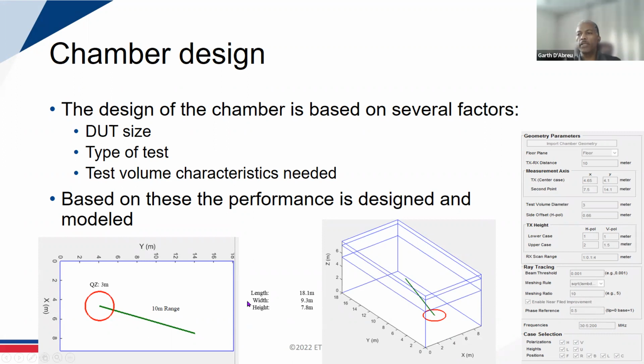This is just one example here based on a ray tracing technique, where if you have information on the propagation characteristics of your measurement or transmit or receive antenna, you understand the volume within which you are interested in seeing what sort of reflections you're receiving, and you have information on the reflection and absorption characteristics of your absorber lining, then you can use a basic ray tracing type approach and calculate, based on the energy in each ray that is incident on the absorber surface, that arrives within your quiet zone.